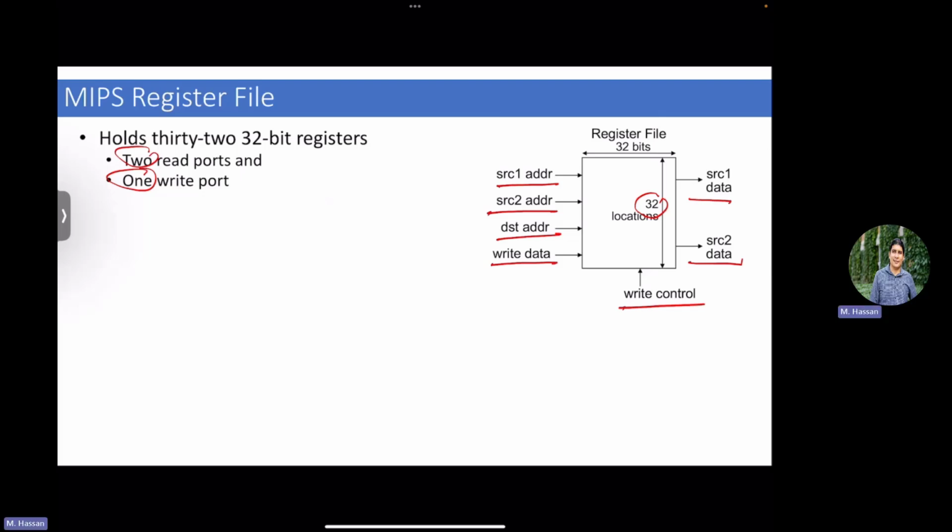Yeah, exactly. At maximum, those instructions would require 2 read operands and 1 destination output. Some instructions will have only 1 read operand, but at maximum you need 2. So if you were to build a register file with only 1 read port, what would be the cost of this? What is the trade-off you are making here? First of all, what do you gain if you build only 1 read port? So compare a register file with 2 read ports with a register file with 1 read port. Why might 1 read port be beneficial?